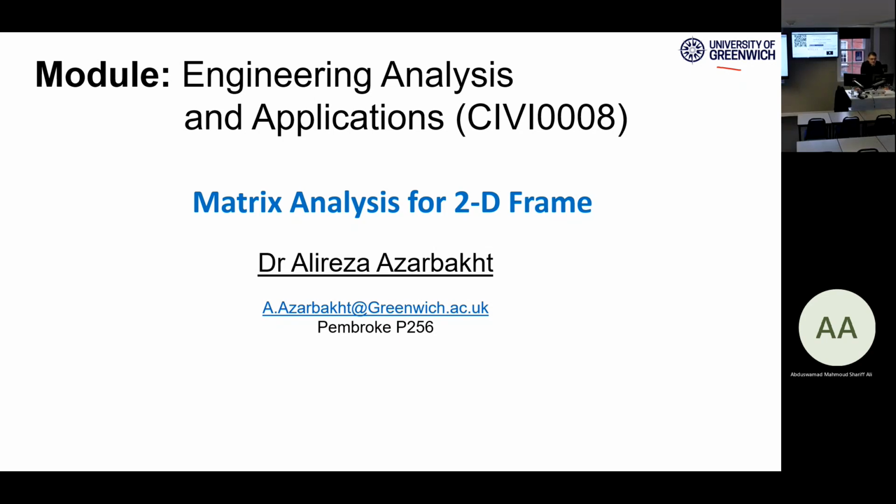If you remember, we had truss structures in the last session in 2022. Remember, the truss structure had generally 4 degrees of freedom. It means that if any element in the truss structure had 2 joints, every joint had the possibility to go through X and Y, right? It means that 4 degrees of freedom for one truss element, right?